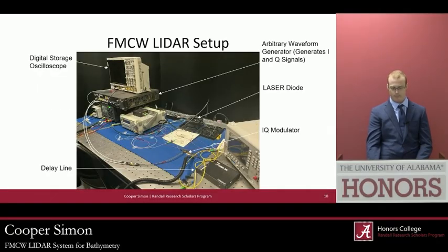So the setup, in the top left, there is a digital oscilloscope, which is used to find the frequency difference and thus the range. Below it is the waveform generator, which generates the frequency waveform. In the bottom right, there's the delay line, which simulates the target. Above it and slightly to the left, the silver object is the modulator that mixes the frequency waveform with the laser.